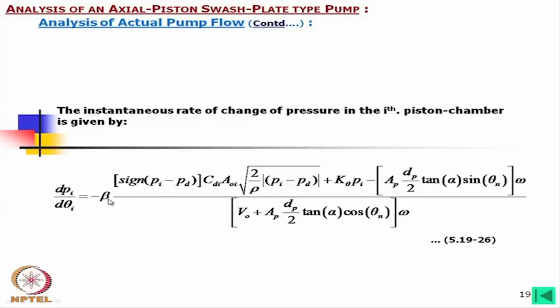This again varies with temperature and pressure of course, but for a pump performance within a range, maybe a temperature range from ambient to 45 degrees centigrade to 70 degrees centigrade, and pressure may be varying from 0 to say 15-20 megapascals, we will consider only one bulk modulus for such oil.